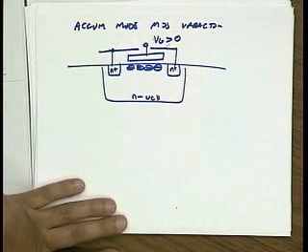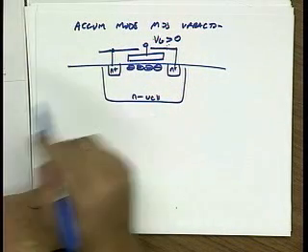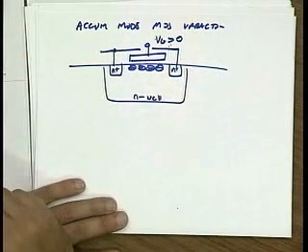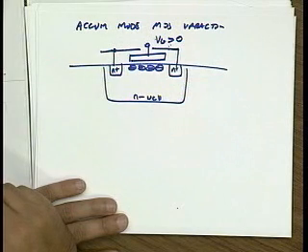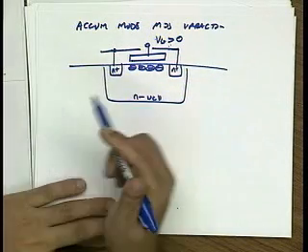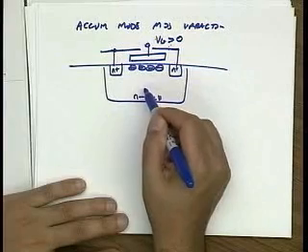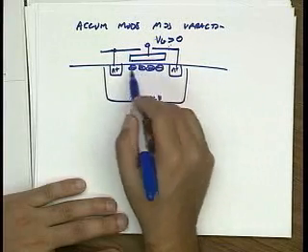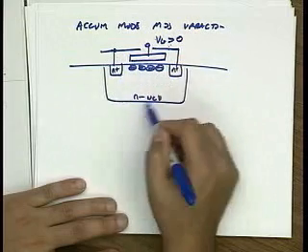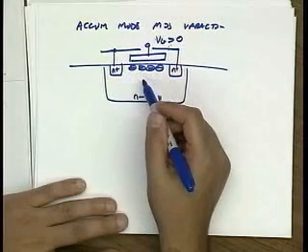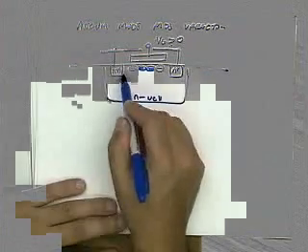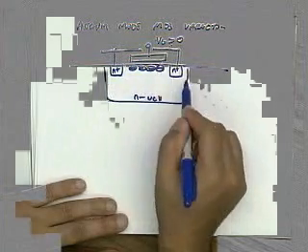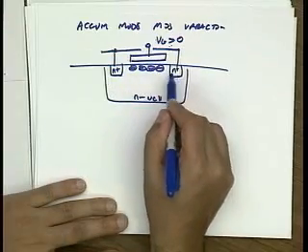And actually, doing this has another benefit. The benefit is that this thing at high frequencies will not invert. Okay, why is that? Yeah, the holes here are thermally generated. So to get inversion, you need holes here. And holes, the thermal generation process is pretty slow. Last time we made that fast by putting P+ contacts here, right? That's how we build a transistor. But we get rid of those P+ contacts and just use a bulk connection.